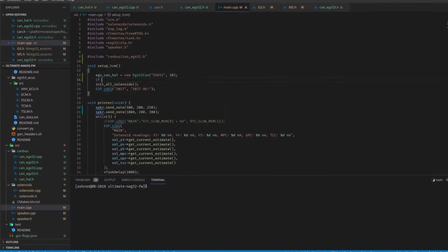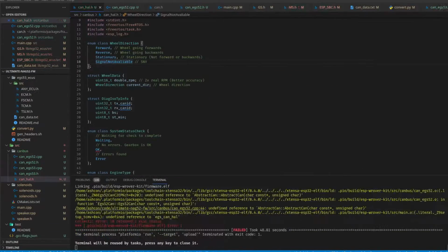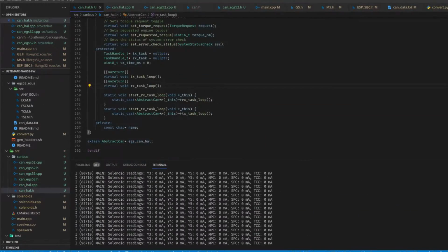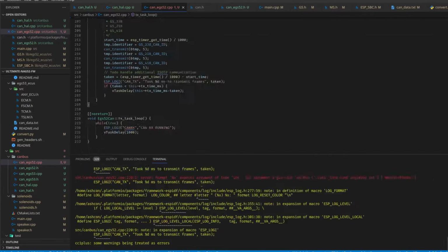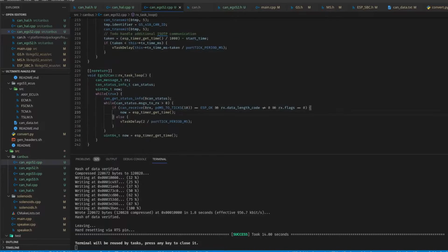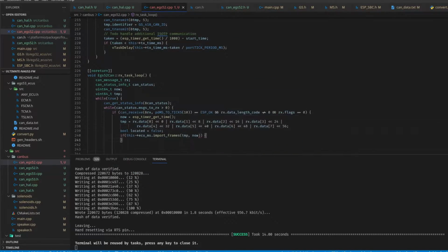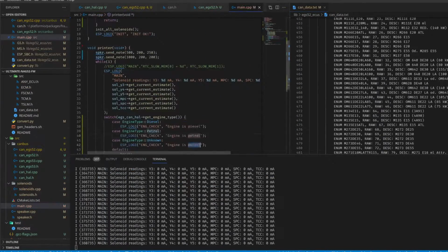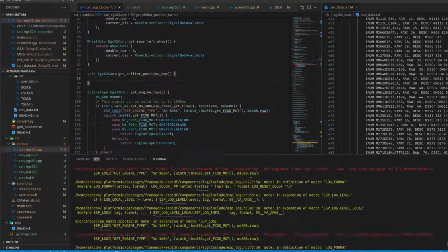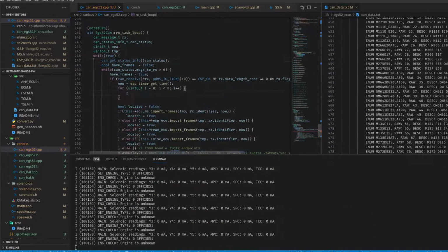And so, after many hours of programming, I finally had the first signs of CAN interfacing with my car. Here on my test instrument cluster you can see the instrument cluster showing agility mode on the gear display. A huge part of this CAN programming was writing the logic which signs the data sent from my TCM so that the engine's ECU is happy with what I am sending and does not think the data is corrupt. Should the engine think that data coming from my TCM is corrupt, it will enter limp home mode.